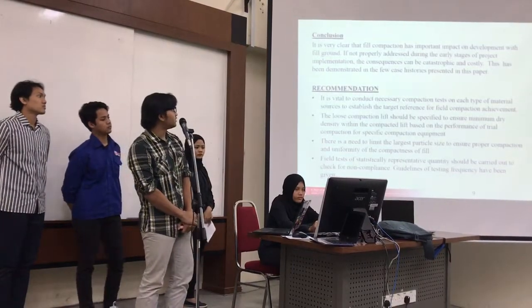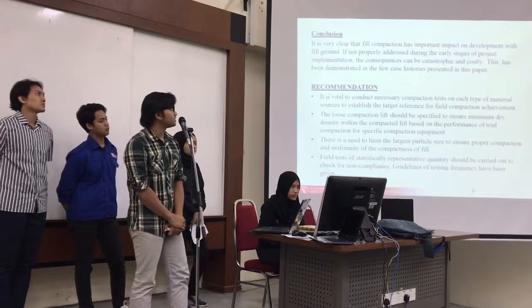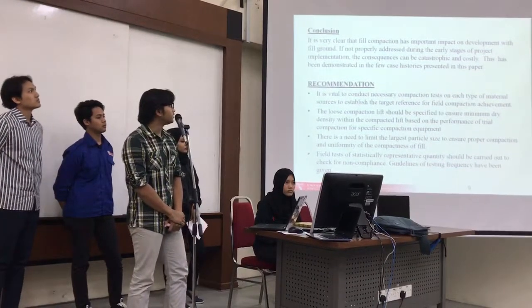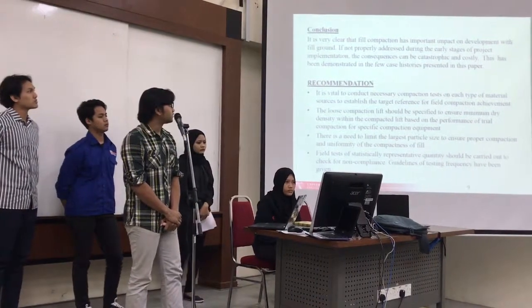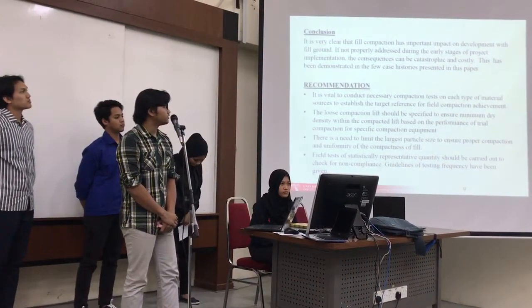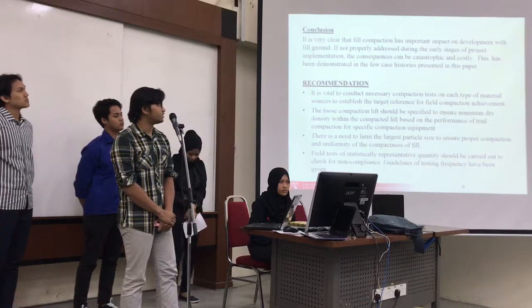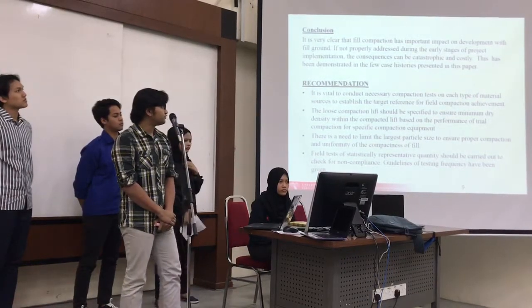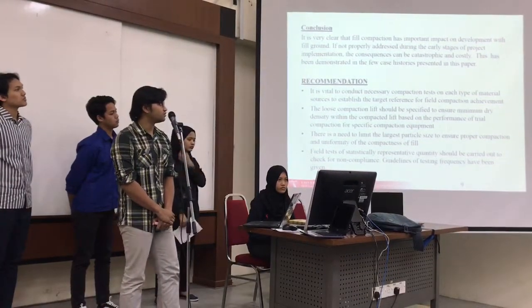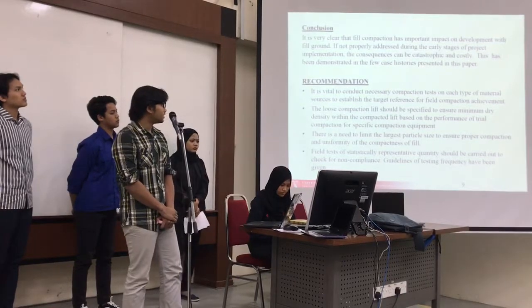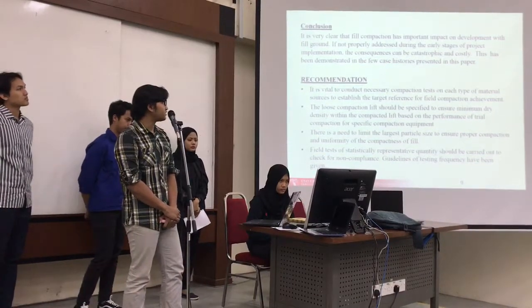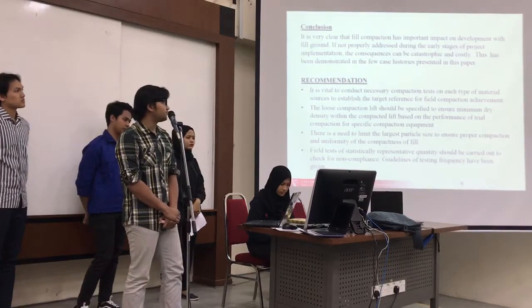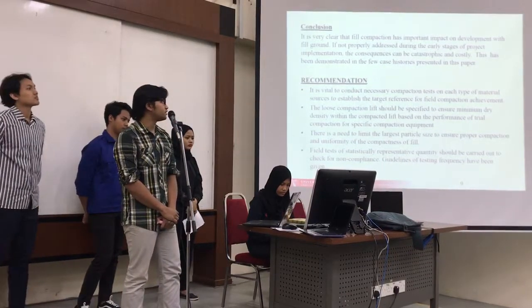So to sum up, it is very clear that field compaction has an important impact on development on filled ground. If not properly addressed during the early stages of project implementation, the consequences can be catastrophic and costly. This has been demonstrated in a few case histories presented in this paper. For the recommendation, it is vital to conduct the necessary compaction tests on each type of material source to establish the target reference for field compaction achievement.